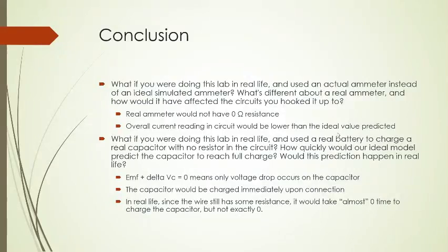What if you were doing this lab in real life and used a real battery to charge a real capacitor with no resistor in the circuit? The EMF plus delta voltage equals zero means that the only voltage drop occurs on the capacitor. Therefore, the capacitor would be charged immediately upon connection. However, in real life, since the wires still have some resistance, it would take almost zero time to charge the capacitor, but not exactly zero.